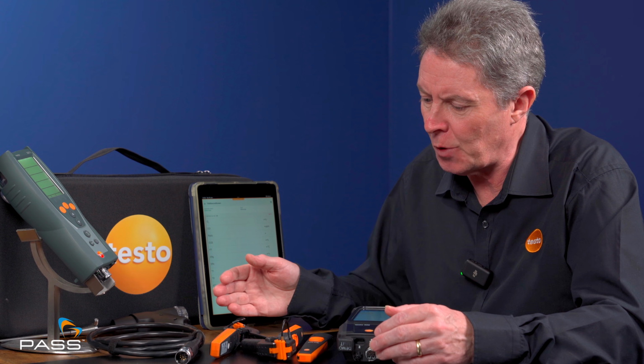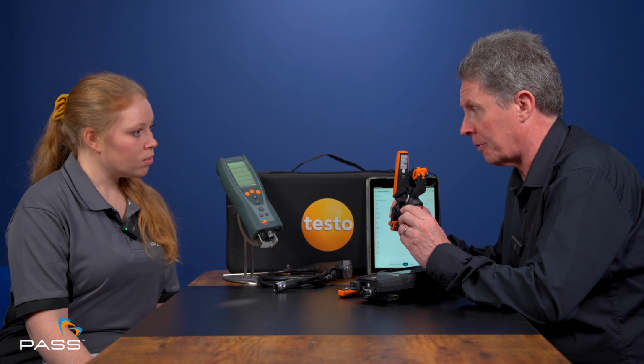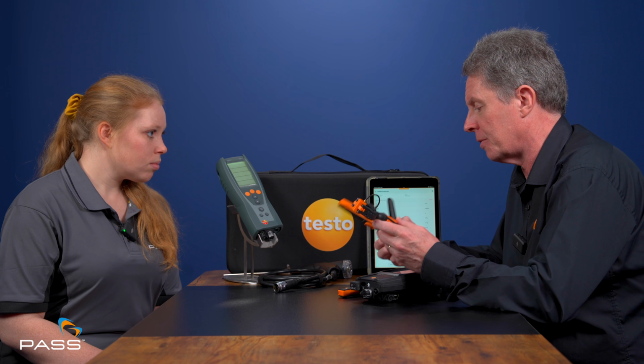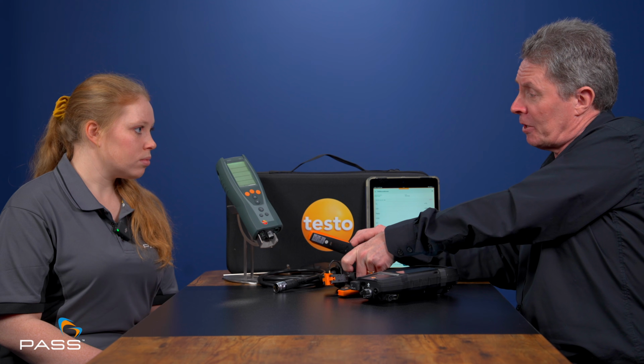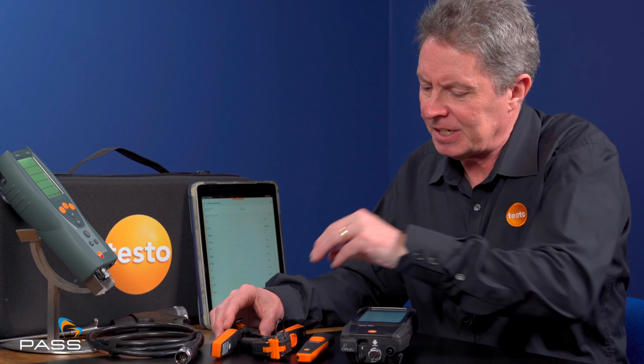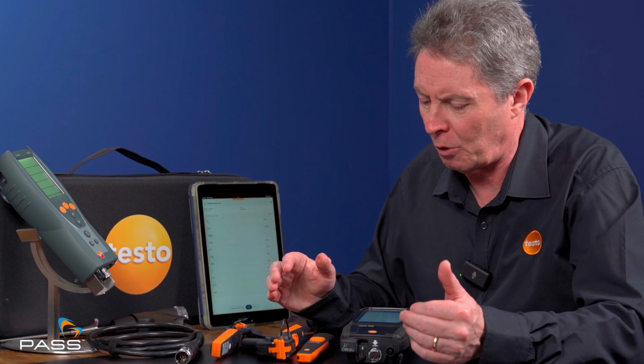If we go to a straight heat pump, something like a basic monoblock, an engineer is going to need no more really than a couple of clamp probes, because he's not going to be breaking into a refrigerant circuit. So it's flow and return, possibly something like the compressor current. If it's an engineer who's looking to really gear himself up now, there are several options.